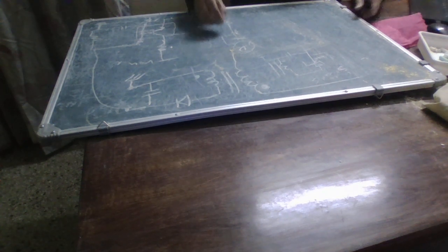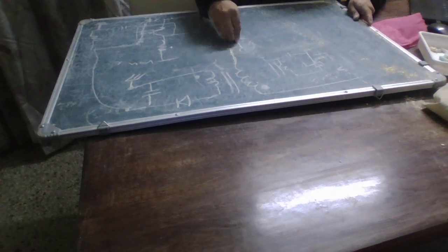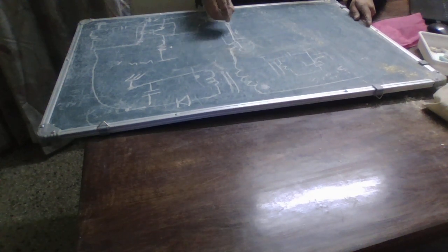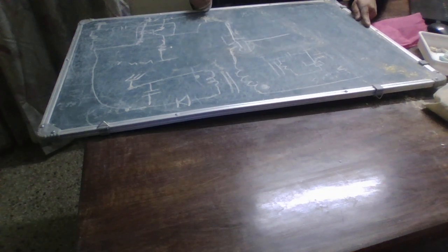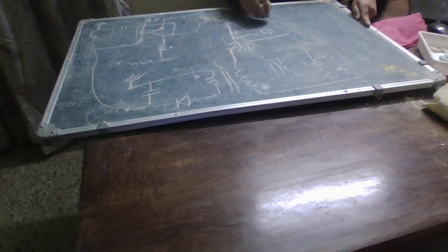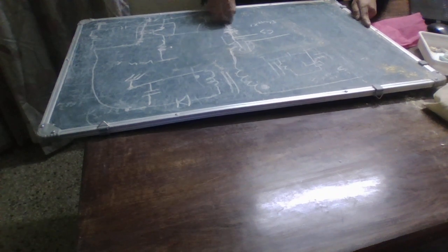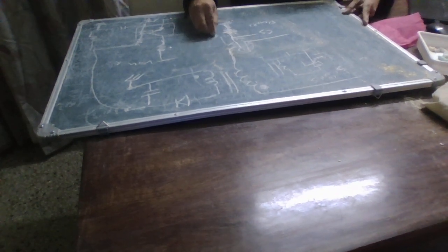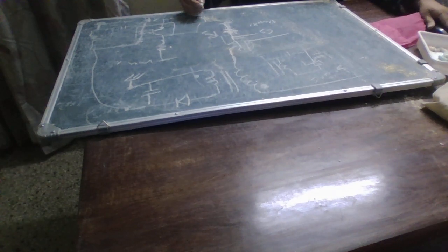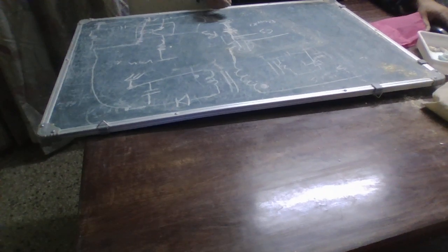So I have a flyback transformer here, and a MOSFET, and in the MOSFET the gate will be driven by the gate pin. There is a CS pin here, and this is the peak GND pin of the IC. In between, we are going to connect a resistor named RS. The work of this resistor is basically current sensing.